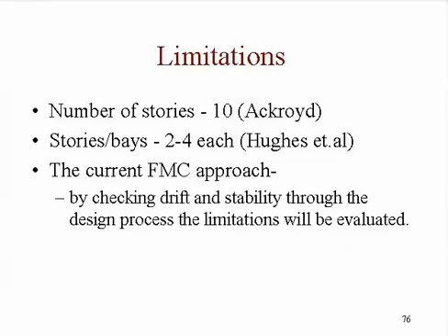There have been a number of studies that looked at the type 2 with wind approach without the stiffness and the stability checks, simply the beam design and the connection design approach. A study done by Mike Ackroyd indicated that these structures should be limited to 10 stories. If you take the studies for the British system, they simply said from 2 stories to 4 stories and from 2 bays to 4 bays. And so they had a very narrowly defined system.